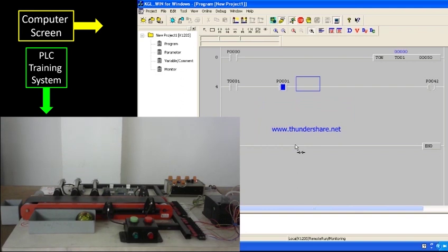So currently here is the signal scenario. P1 is receiving signal since it is a normally closed contact, and the timer has a count of 00 initially. Now if we press this button here, the timer will start counting upward, that is from 0 to 50. Let's see what happens. So if I press this here, you see that the timer is counting up, but when I release it, it goes off and resets to 00.